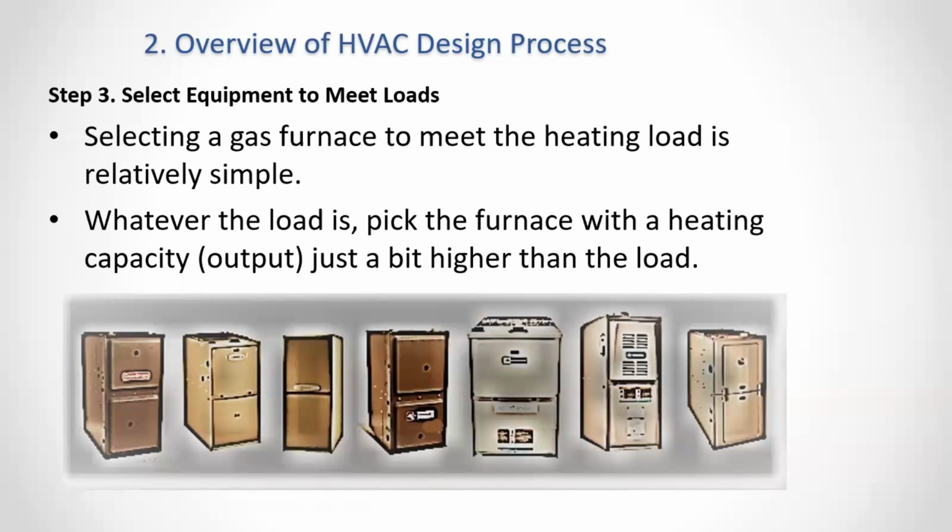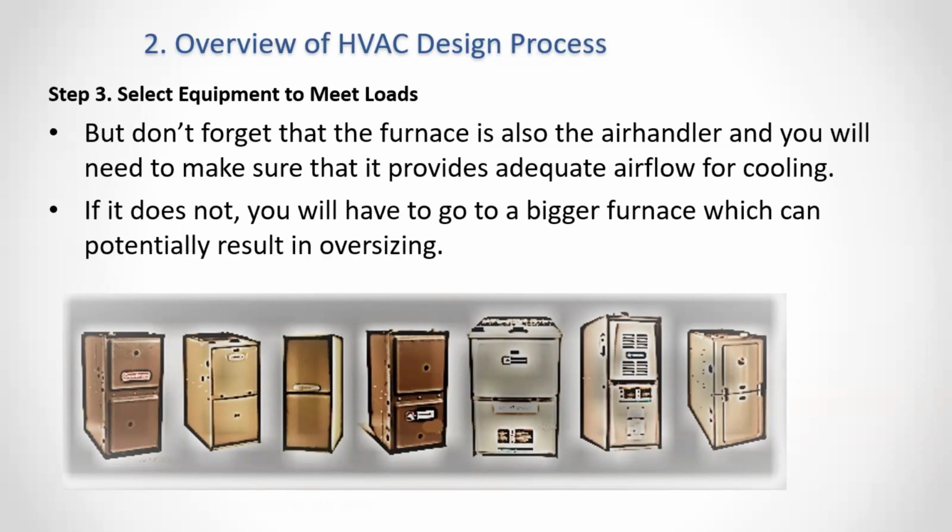So gas furnaces, they're easy. They're just dumb beasts. You just hook them up, they shoot out flame and make the place hot. But that's at the expense of safety and greenhouse gases and all that other stuff. So gas furnaces are pretty straightforward. Next slide, please. Don't forget that your furnace is also your air handler. So if you have air conditioning, you have to make sure that the furnace will provide enough air. Next slide, please.